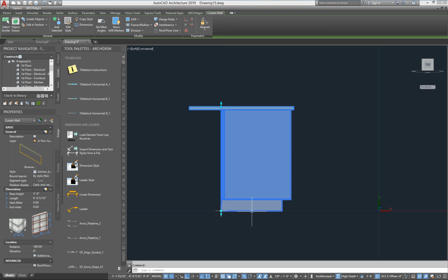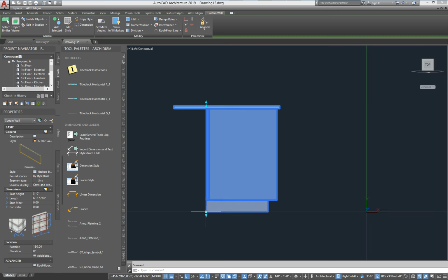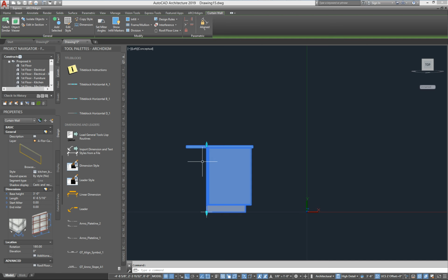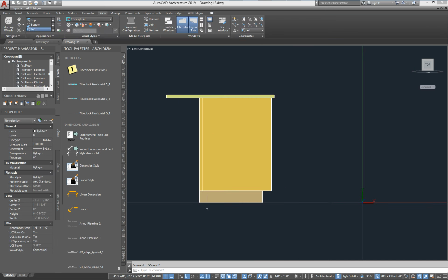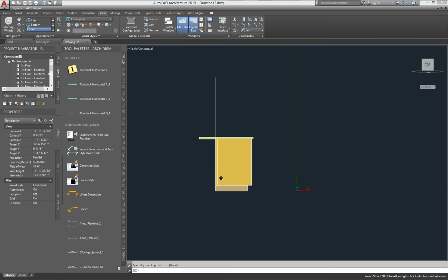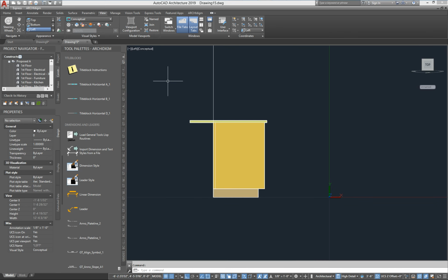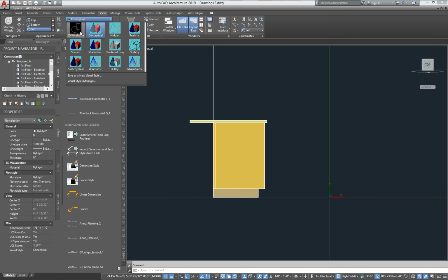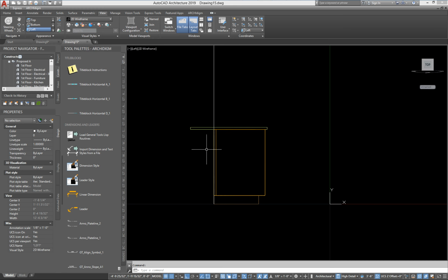By default, a curtain wall will want to go through the center. That doesn't really make sense when you're doing cabinets. Most of the cabinets are drawn along walls, so we use the back side as the baseline when you're drawing it. That serves as where this curtain wall kind of sees itself, as a reference point.